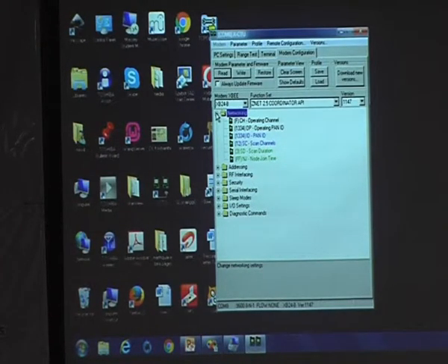So what is a channel here? Obviously, the wireless communication medium works, or data transmission takes place, in terms of channels. Now how many channels are supported over here? The ZigBee protocol, or more specifically the XBee module which you are trying to see here, does not have 100 channels available. There are only 16 channels available. Please make a note, 16 channels are there. You may use one of the channels for your communication setup of the corresponding wireless sensor network.